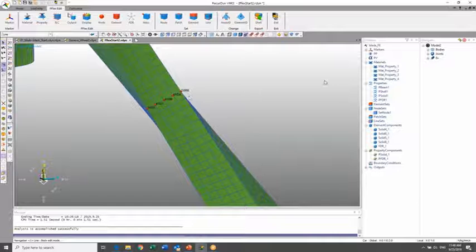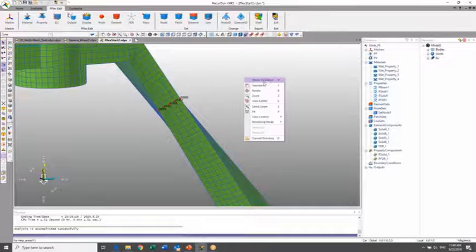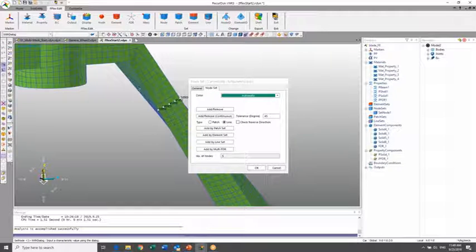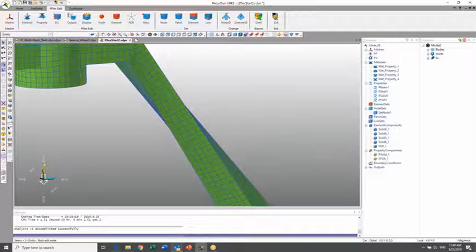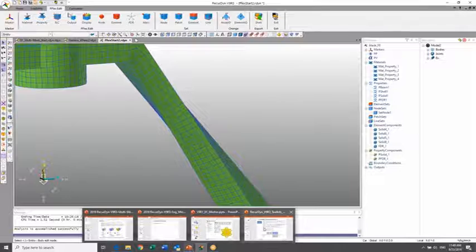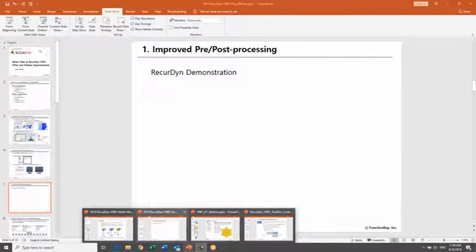And if you click on one of those nodes, it will create a line and add all of the nodes that are in that line. So it adds in one direction, and it goes in each of those directions. It's a quick way to add all the nodes that are in a line there. So just finish operation, and then you have your node set there.